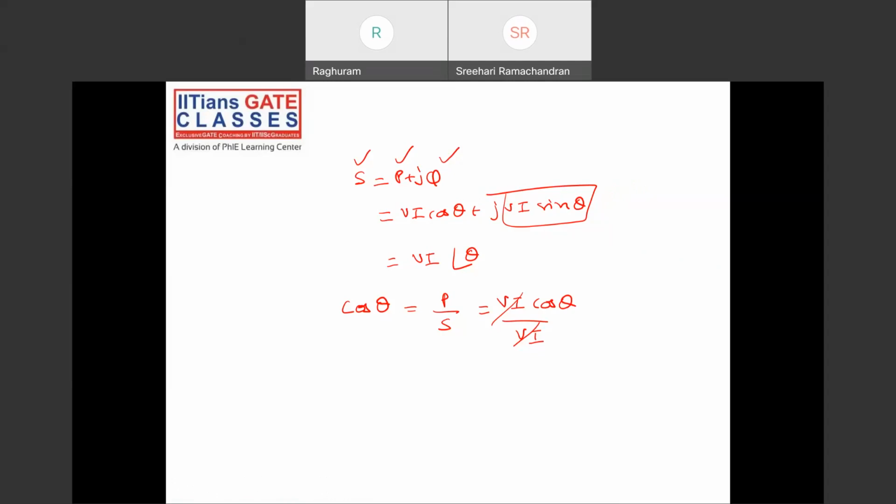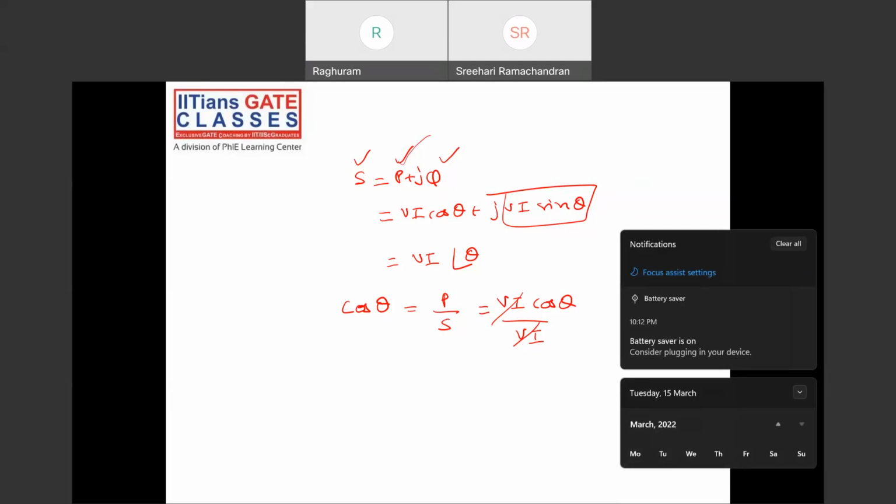A capacitor only stores energy, and an inductor only stores energy. An inductor stores energy in the form of a magnetic field, and a capacitor stores it in the form of an electrostatic field. So they both are energy storing elements. Only the resistor is an energy dissipating element. All the actual work done can be represented by the resistor only. That is why P is called real power or active power. Q is only reactive power. It simply oscillates between the source and the load.